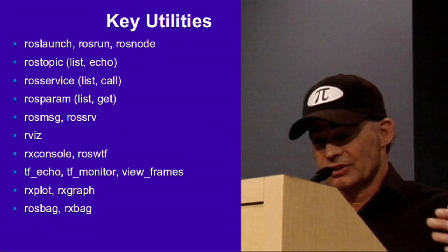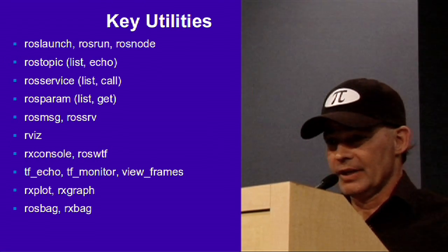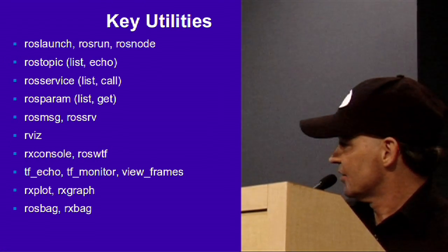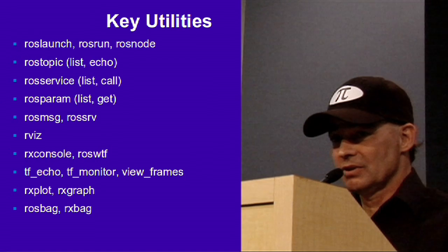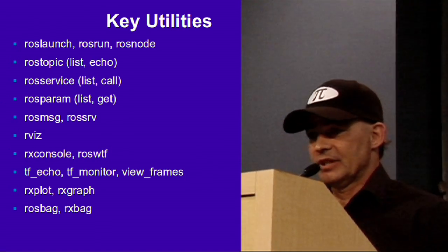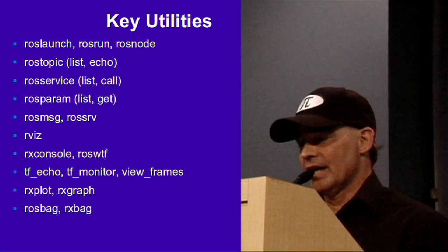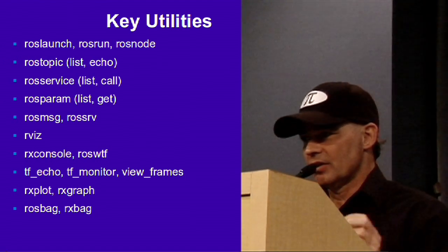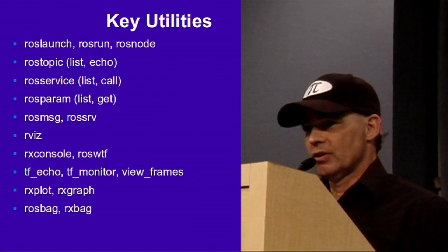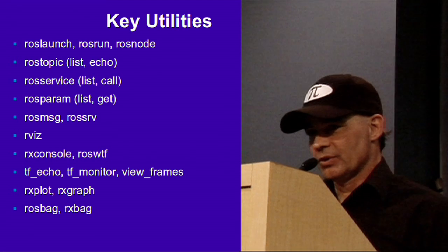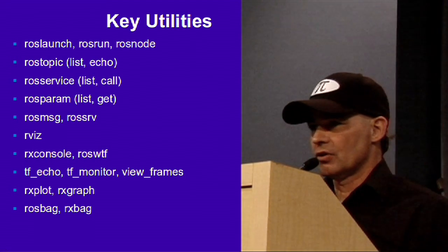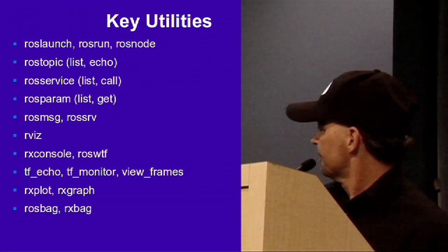Because normally one would just run one program and everything goes. And the answer is a launch file, which is just a simple little text file with one line typically for each node that you want to run, but then it's all there in one file. And if you want to change one of the nodes, you just change that node specification in the launch file and relaunch the whole launch file, and it does all the node launching for you.